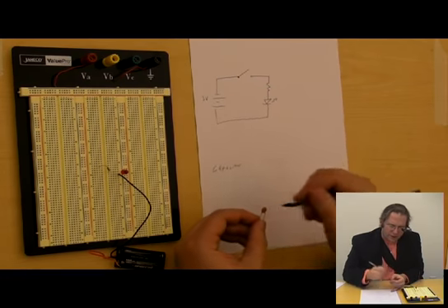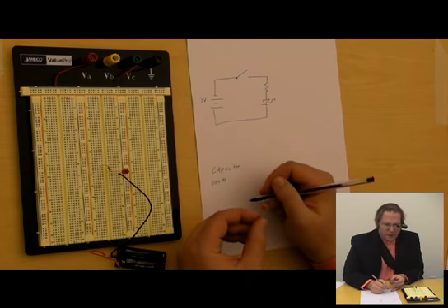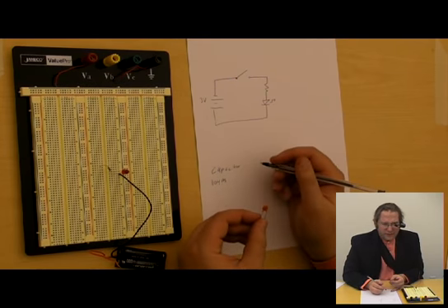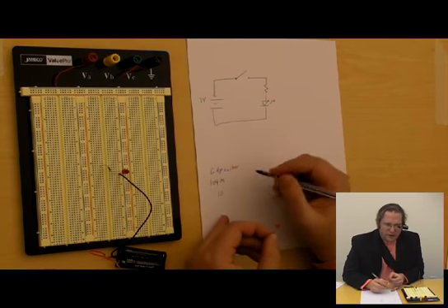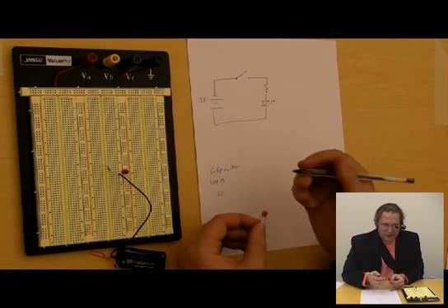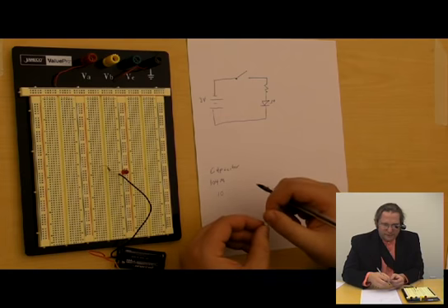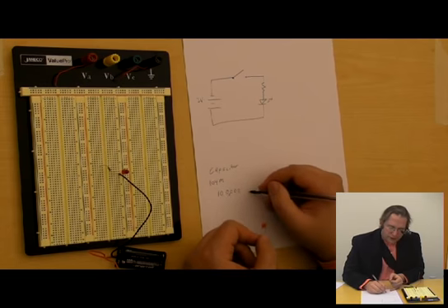So how do I know what value this capacitor has? 104M. Well, what it is, again, like the resistor, is that it's the first two numbers, 10, followed by the last number, which indicates how many zeros are added at the end of it. So in this case, it would be 4: 1, 2, 3, 4, and the unit is in picofarads.